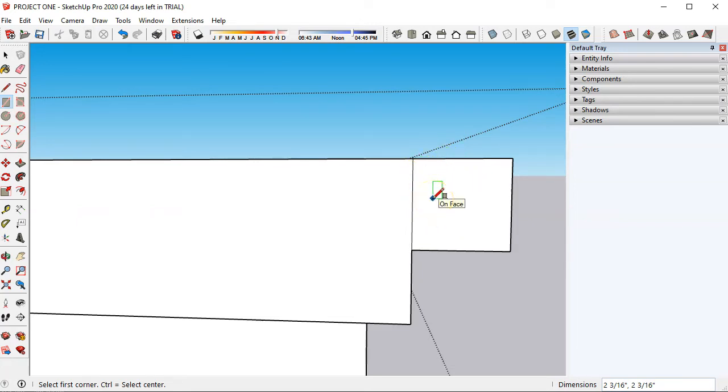With your illustration, it shows that the first line that comes out here is 1 3/4 of an inch from this point here. So you can use guidelines like this and go out 1.75, enter. Okay, and that's 1 3/4 of an inch.